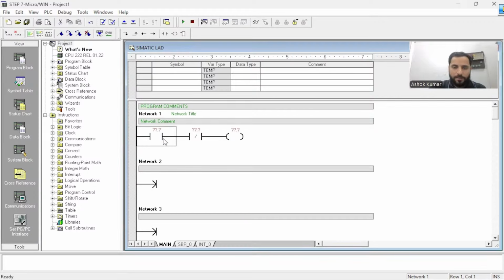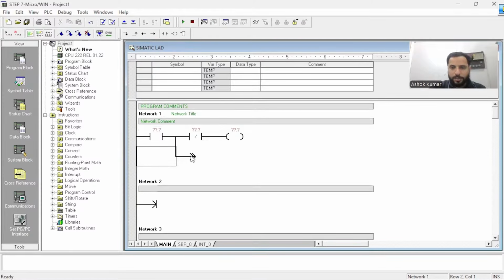If you want to take a parallel, select this parallel, line down, line up. So take line down, although the arrow is showing this way, but I have to connect something here. So select your cursor at this point, the arrow is moved to here. Now, if we have to connect something here, let's put the cursor here and place NO or NC, whatever you want.